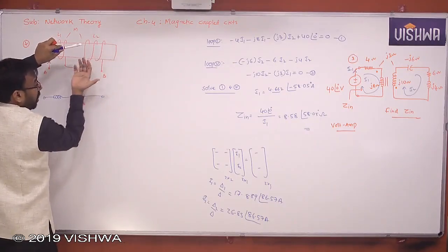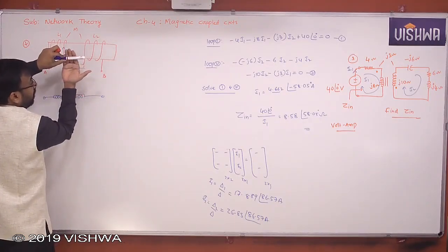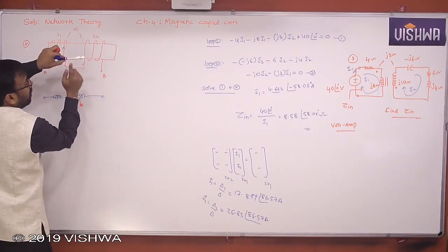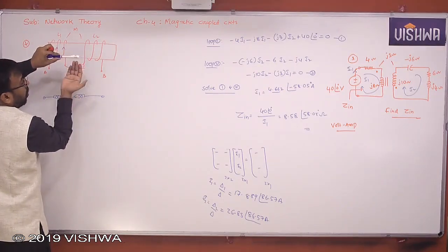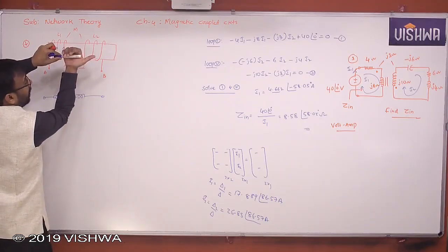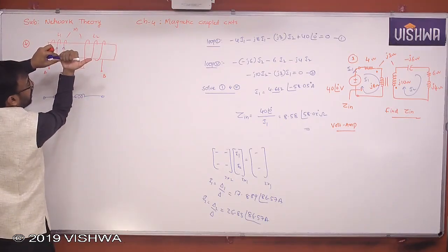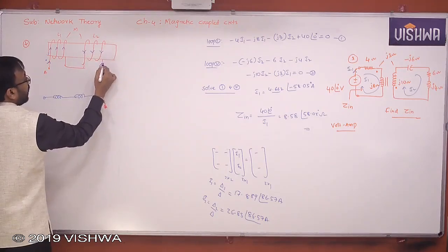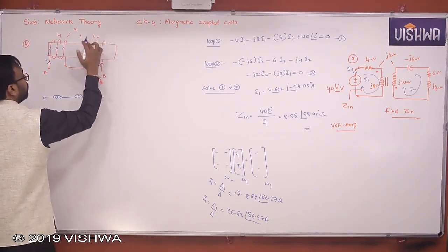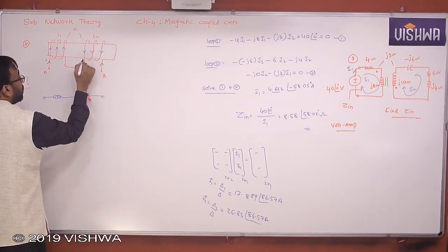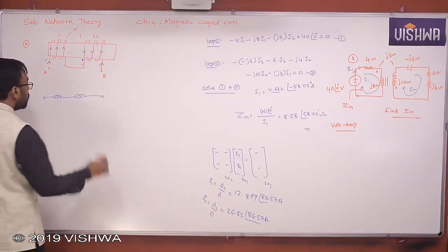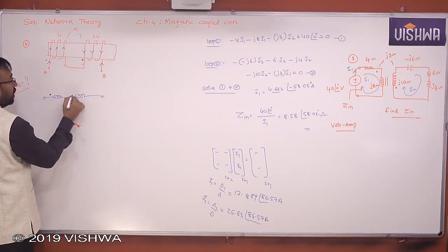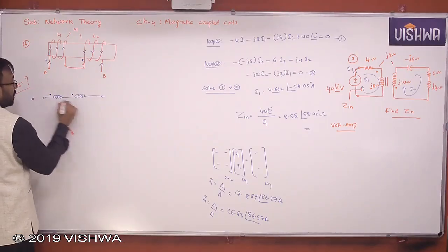Knowing the flux, you can find the current. Current in the backside part of this particular non-magnetic core is upward, but on the front side of the winding you will see downward. That means this way. So where is it entering? Entering here, leaving here. So here is a dot, here is a dot. So these are the terminals.